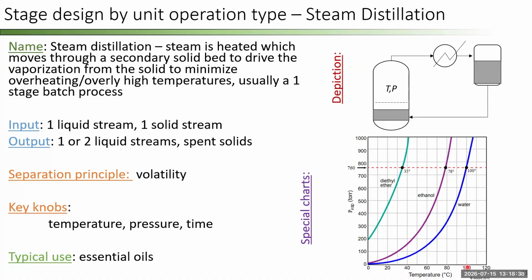I've lowered the maximum temperature that my plants are going to be exposed to. I could also change my carrier gas, that water, for ethanol, say, and now the maximum temperature they'll see is 78 degrees centigrade. All right, so if I know the vaporization temperatures of the oils that I want, I can start playing around with how I'm pulling them out.